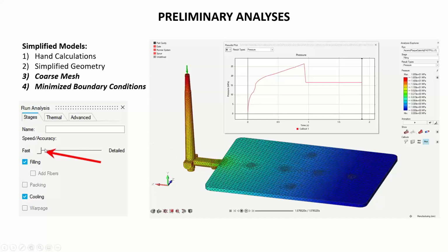But this is a solver that, in our solution, we use the fast solver, and this solves in much less time than trying to do a full simulation with 4, 5, or 6 layers of elements everywhere in this model. I get very similar results, and it does it much quicker.